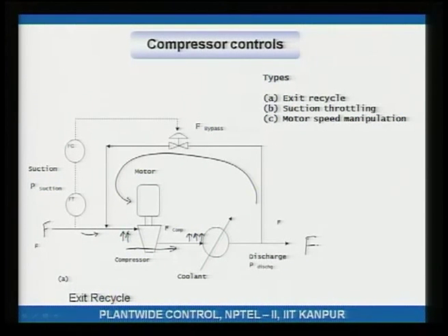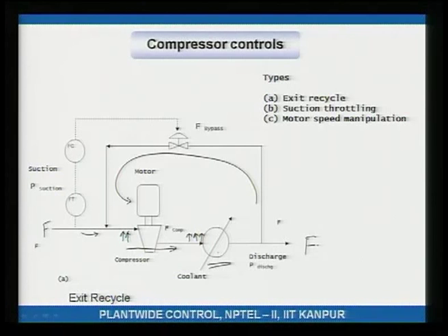What I am essentially trying to say is the temperature of the gas, if you do not have this cooler, will increase non-stop, if I assume that the heat losses are negligible. There is energy feedback because of this recycle. To break this energy feedback, this cooler is provided, probably with a temperature controller. The point is, this cooler prevents the energy from building up.